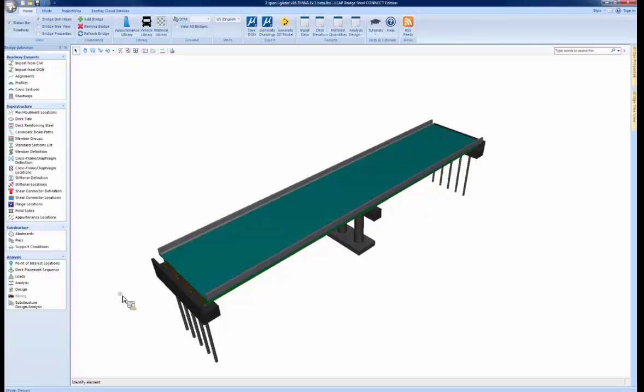Okay, does the optimization consider the erection stability, especially on curved girders? And the answer to that, Bill. Yeah. The only optimization considerations are whatever's in the AASHTO specifications with the code checking. So if there are any concerns about secondary effects or nonlinear effects, something like that, no, that would not be considered. Just whatever's in the AASHTO code checking.